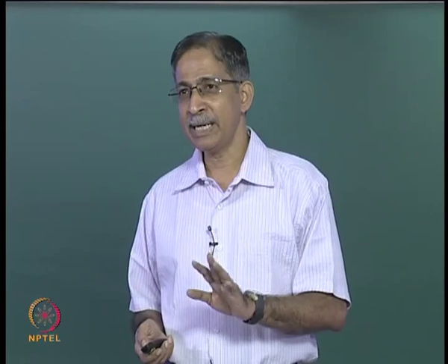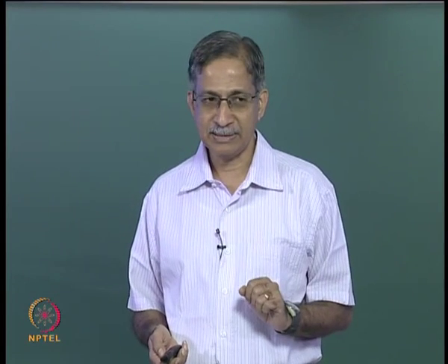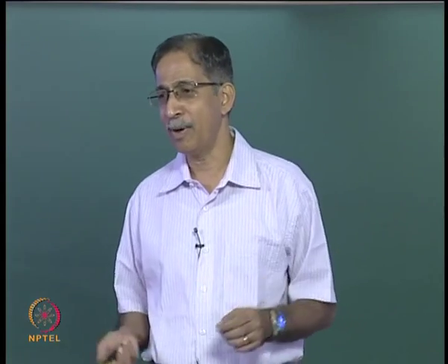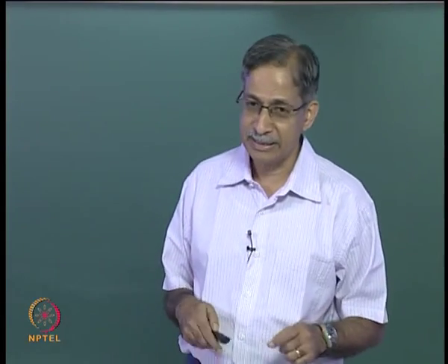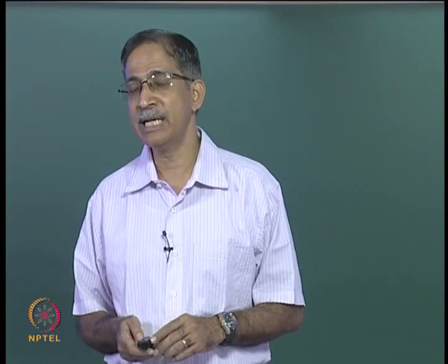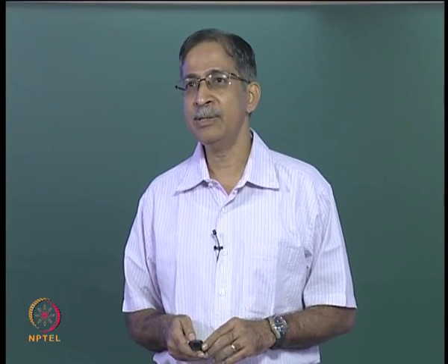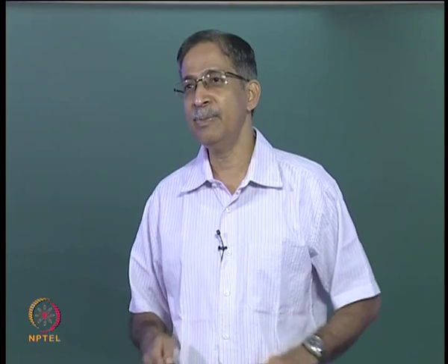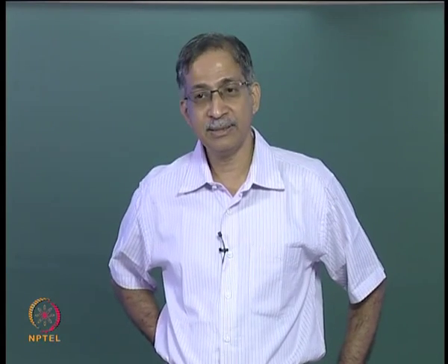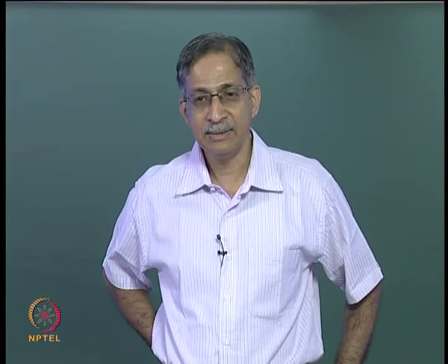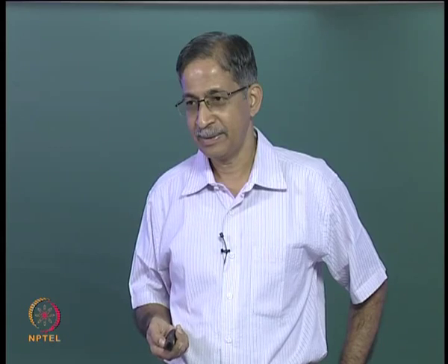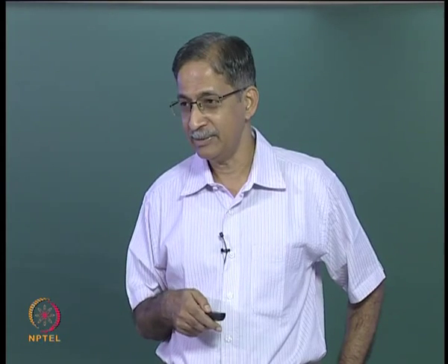Now if you recall, we did this problem in the last class, and we will now look at more problems. We will try to do 3 quick problems in this session. With that we will close the reduced element stiffness method. We need to worry about how to deal with moment releases. There are 2 kinds of moment releases that you can get. One is when the far end is a hinged or roller support. The second is you have an internal hinge.